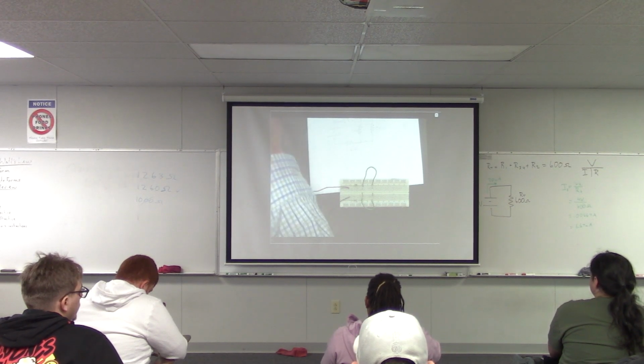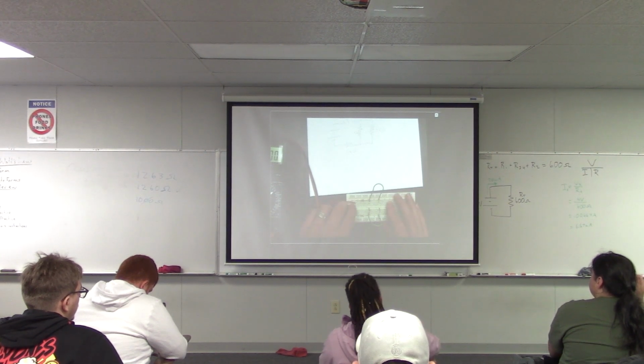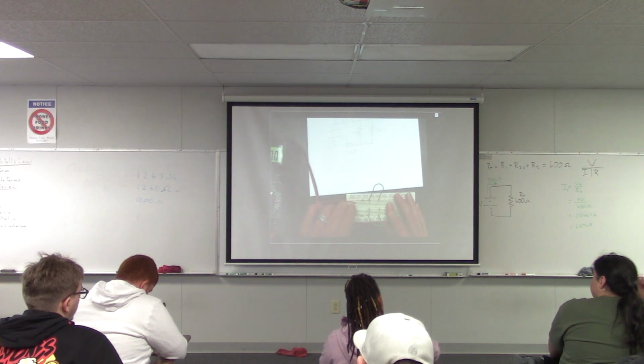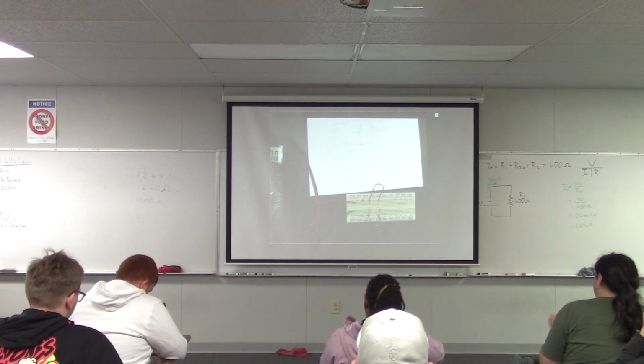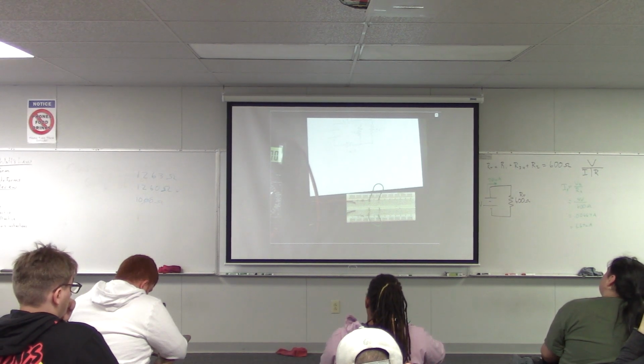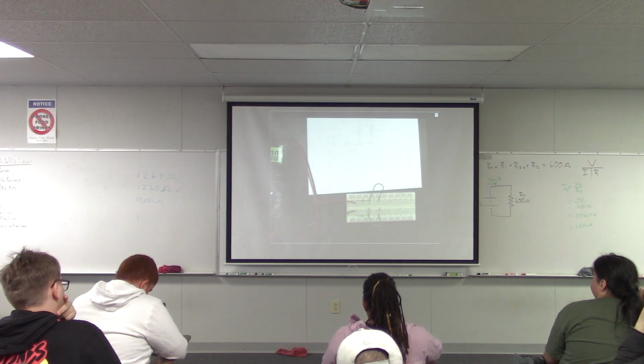All right, and then the other thing is that you want to measure the current for your circuit. So the way that you measure current is you have to partially deconstruct your circuit. And then you attach your meter to the two loose ends of the circuit where it was taken apart. So for instance,